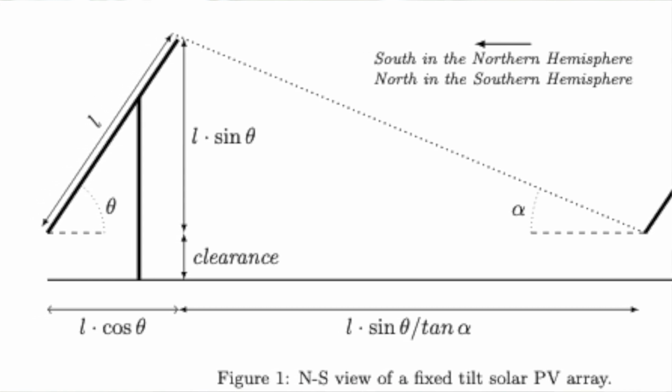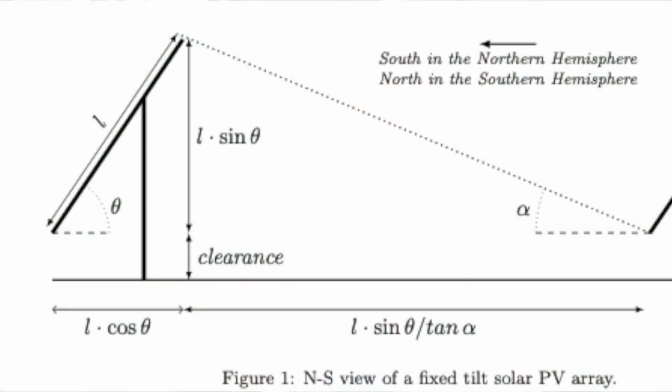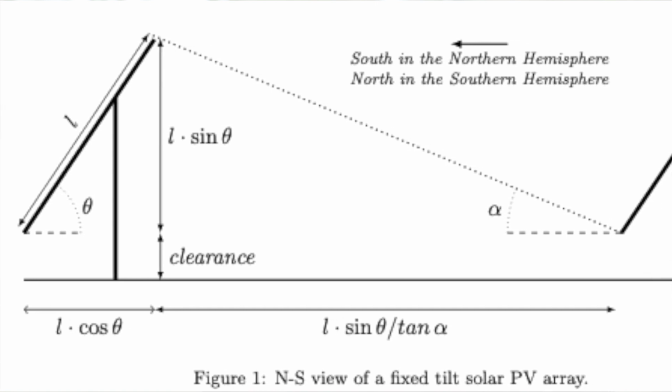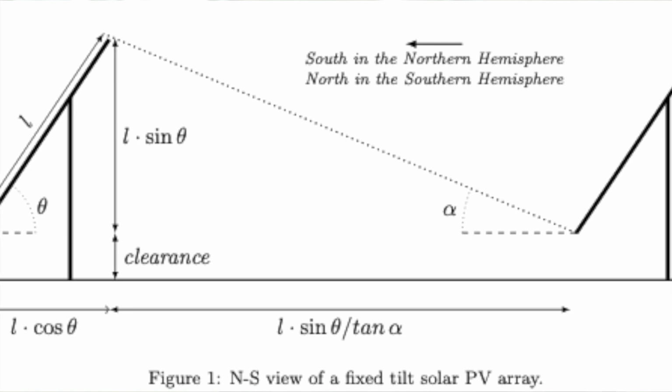But it's not just that. We're also going to be talking about the minimum sun angle, which designers sometimes use to define the inter-row spacing between the modules. So, what is minimum sun angle? If you install a flat module that's facing straight up, so it has a tilt of 0 degrees, this module is geared to capture summer light. In other words, the sun is very high in the sky when it's producing most of its energy. If you break down its energy through a histogram, you'll find that the sun altitude is quite high for most of the time it's actually putting out power. On the other hand, if a module is tilted, it's more geared for lower sun altitude, meaning that it will require a lower minimum sun angle in order to capture light. And that's what's happening when you increase the tilt angle. So an increased tilt doesn't just cast a longer shadow, it requires the inter-row spacing to be greater.